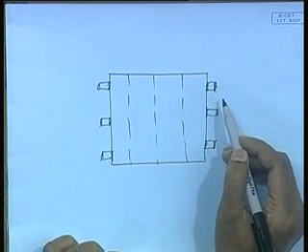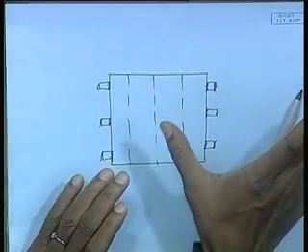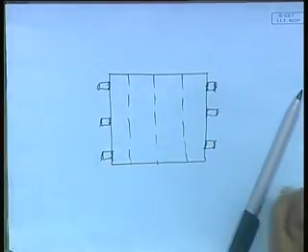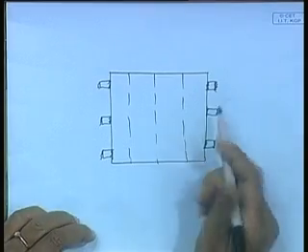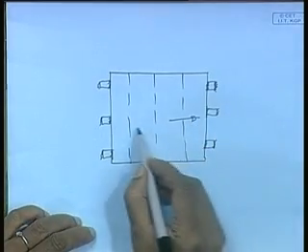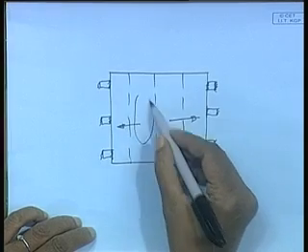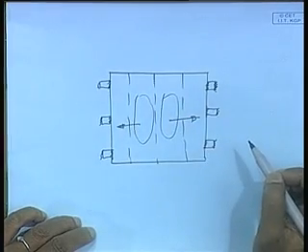What am I basically doing? When I am heating it up, it is expanding and I am welding it. When it cools down, it will contract, it will put the plate in tension, it will put sufficient tension force so as to mitigate the effect of buckling here.